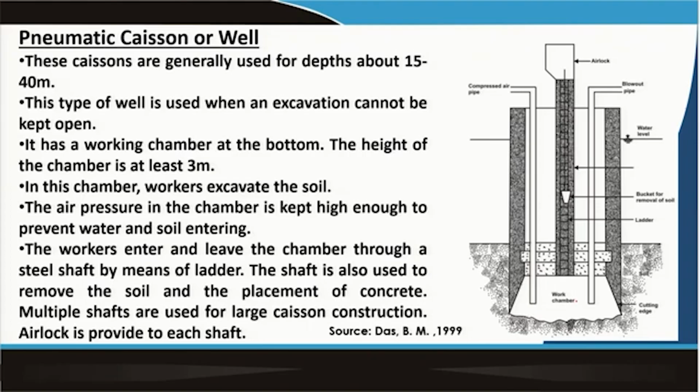So, there will be a shorter duration of the working period for the worker, because we provide very high pressure within the working chamber. Now, there is a shaft, and within the shaft there is a ladder. So, the worker can leave and enter the chamber through this shaft by means of the ladder. This shaft can also be used to remove the soil and for placement of the concrete.